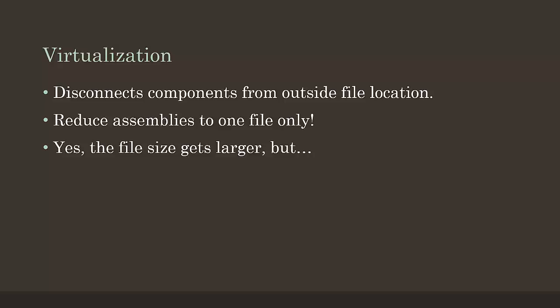I like using this because it is an assembly. Everything works in it like an assembly. Everything works. Your mates work. Everything. So if you like configurations, add configurations. You want to do the flexible subassemblies, do flexible subassemblies. Everything works. There is one downside to it, and I'll show it to you here in a second.